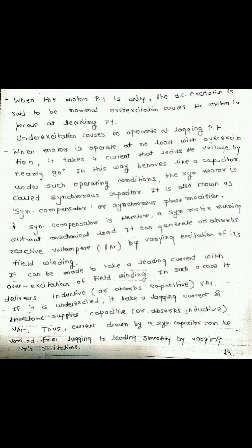Basically, if the load has a lagging power factor, then this synchronous motor will provide a leading power factor. This synchronous compensator is used as a capacitor which will lead the power, and hence the total transfer capability of a transmission line is increased. So this motor behaves like a capacitor.